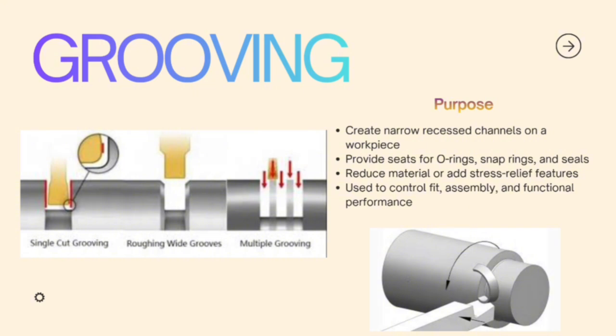In addition, grooving can reduce material or add stress relief features. This means it can help manage material thickness and reduce internal stresses in a part. Overall, grooving is used to control fit, assembly, and functional performance, so it plays an essential role in ensuring that parts function as intended. Next, for the types of grooving operations, we have single cut grooving, roughing wide grooves, and multiple grooving. These methods are selected depending on the size of the groove and the required accuracy.